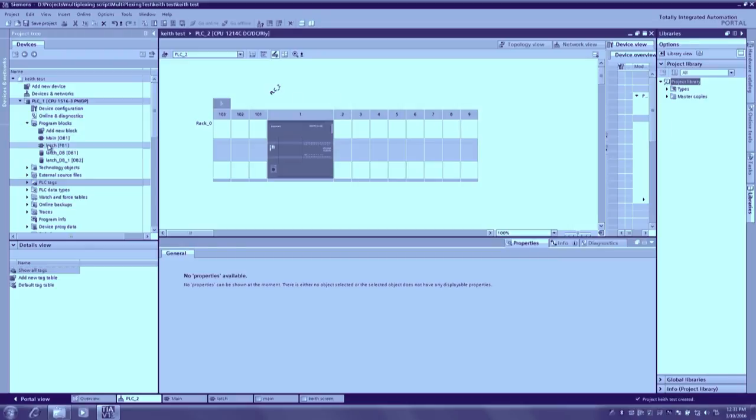So what I want to do is save this latch file into my master copies. So it's saved an identical duplicate of something I've created. I can then take this project library view, this latch circuit, and save it as a global library and publish this out across my servers to all the engineers within my plant. Anything can go into these libraries.